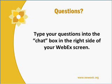Great, thanks. And let's see, we have our last question for you from Gary, who'd like to know if it is more efficient to get water from a surface source than from groundwater. Yeah, that's a good question. It all depends, but typically surface water sources require about 30% less energy than a groundwater source. That's because groundwater has to be drawn from where it's at, and the energy it takes is really contingent on the depth of the aquifer, or how far down that groundwater actually is. So the deeper the groundwater, the more energy it takes to pump it up to where you need it.